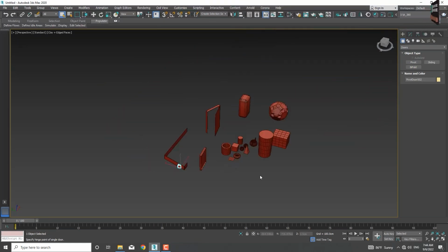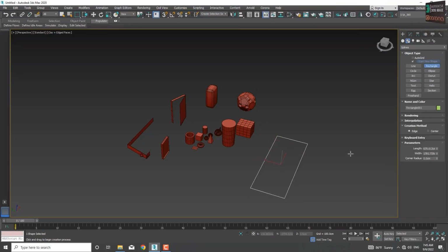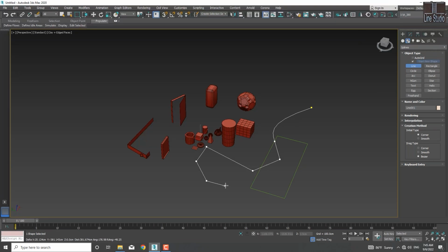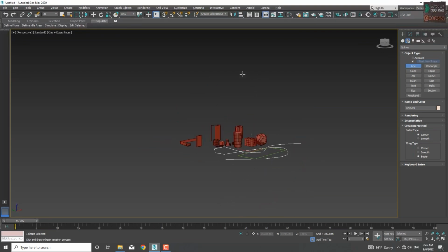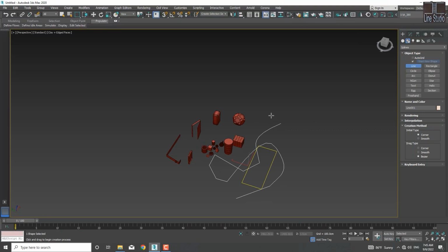This is about the objects within the geometry section. In shapes, we also have shapes like line, rectangle, meaning a rectangle, which only create 2D shapes for us. Be careful not to create lines in the 3D Max environment in perspective, because you might place a point in space and it might not lie on a plane, and it could cause problems for your work.